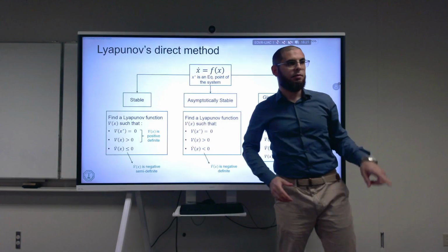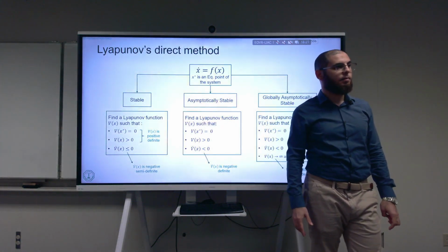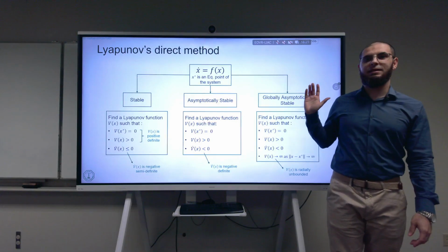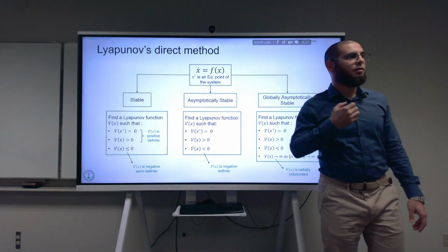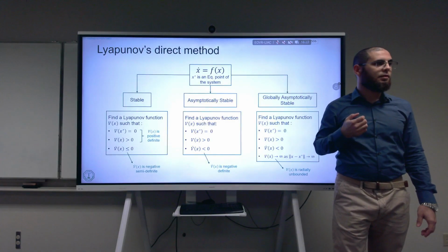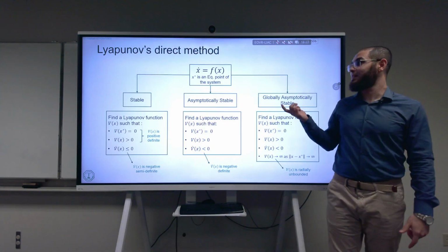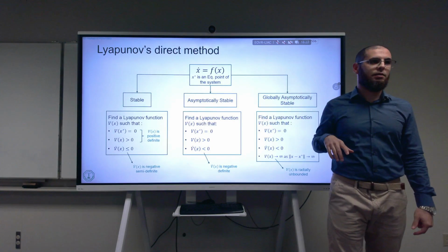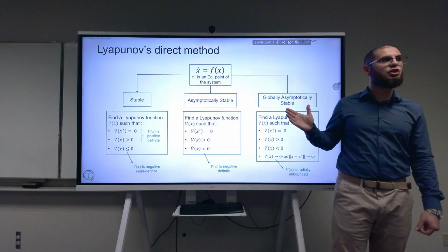I think what Roman actually wanted to ask was whether there is a possibility that someone comes up with a function that shows instability of the equilibrium. That's a very good point. Do you see any instability here? It's not possible. We already said that we can check the instability from the indirect method. The instability you can get from the indirect method, but Lyapunov's direct method can only show stability, not instability. So it's inconclusive about instability. There is no recipe that you can use.